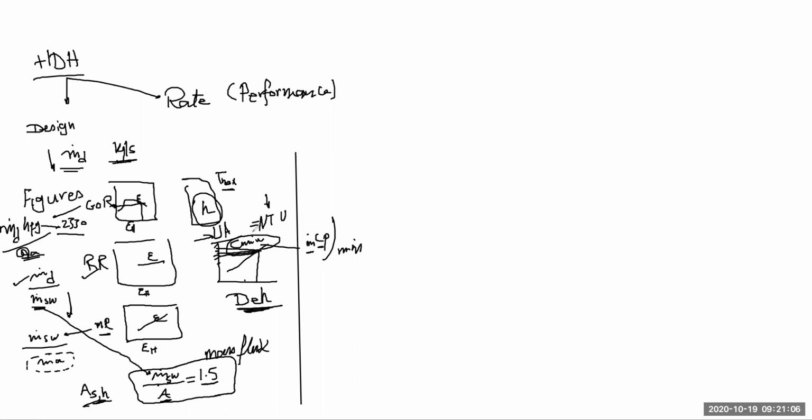Yes, it's basically the same number, but normally the value of the overall heat transfer coefficient is given to you because calculating it is a little bit involved, that you have to go for forced convection inside the tubes and a kind of condensation on the outside surface of the tube. So the correlations would be some sort of a lengthy process, which is not the target. The target is to learn how to calculate the surface area. That's something probably we can ask in a project, that you can calculate the details of the overall heat transfer coefficient.